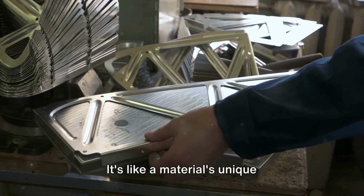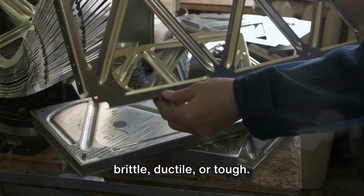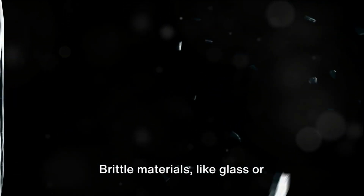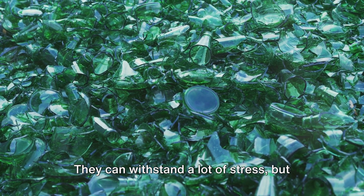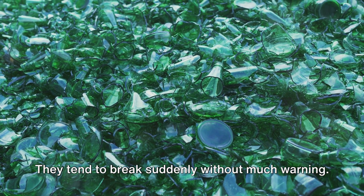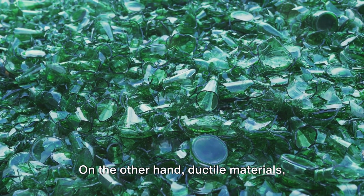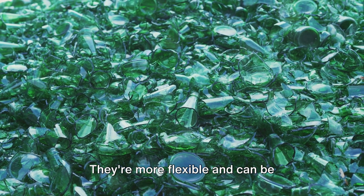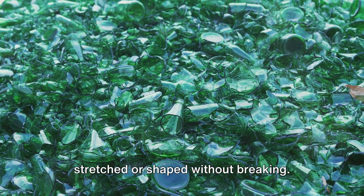It's like a material's unique fingerprint telling us whether it's brittle, ductile, or tough. Brittle materials like glass or ceramics have a high modulus of elasticity. They can withstand a lot of stress, but they're not very flexible. They tend to break suddenly without much warning. On the other hand, ductile materials like gold or copper have a lower modulus. They're more flexible and can be stretched or shaped without breaking.